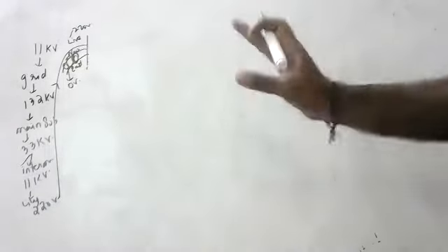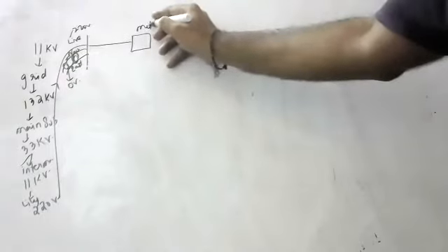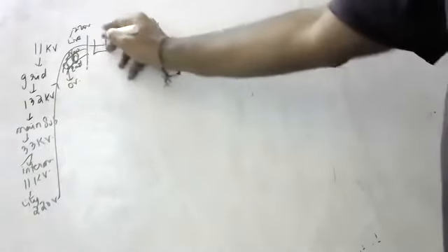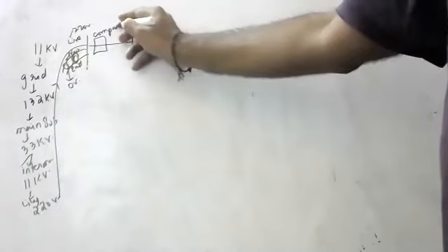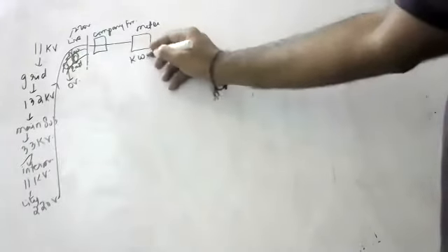Okay, children. Before the cable from the pole comes to the meter in our house, they will put a company fuse, or pole fuse, as I told you yesterday. Only an authorized person should handle it, and the rating of this fuse depends upon how much current we are using in our house, whether it is a house, an apartment, or any commercial thing.